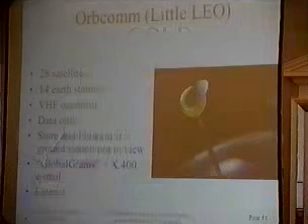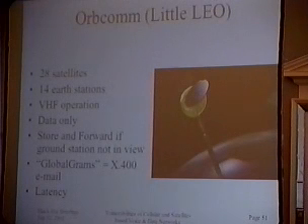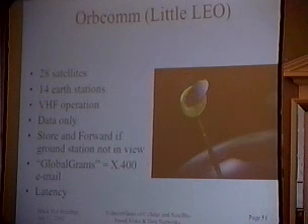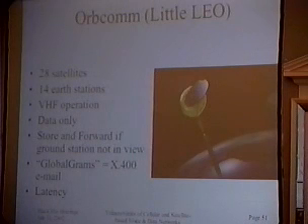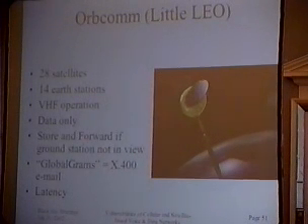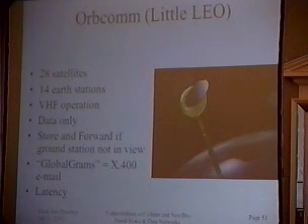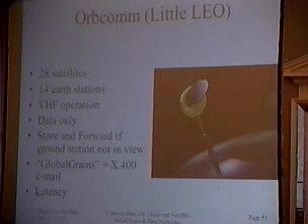All right, after the big LEOs, there is something called little LEOs, and the FCC defines those as data-only services that operate below 1 gigahertz. There's only one that's really in real operation. That's called Orbcomm. They also went bankrupt, and they were also bought by investors, and they are continuing in operation. 28 satellites in low Earth orbit. They operate in the 130 to 150 megahertz band, which is also a paging band, which can create interference problems. The Orbcomm model of moving data is basically by email.